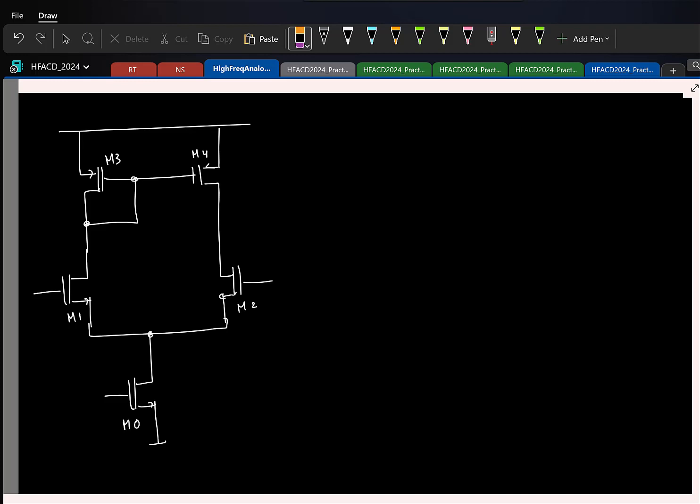So to find the noise voltage, what do I do to the input side? You have to short it. So one difference is, see here we have 2 inputs, right? To model the noise, you can model it as a voltage source either at the non-inverting side or at the inverting side, or you can say half there, half here, doesn't matter. Somewhere at the input we can model this. And once again, to find the contribution due to this voltage noise, we have to short the input.